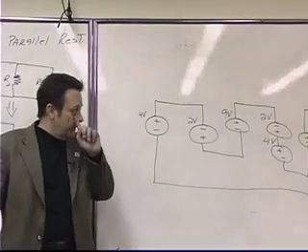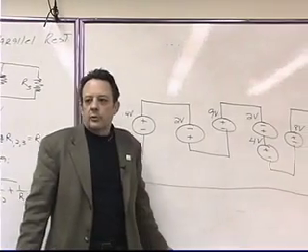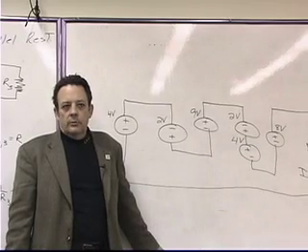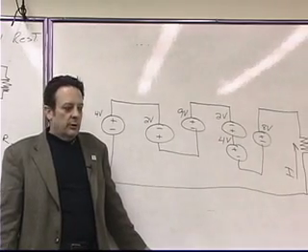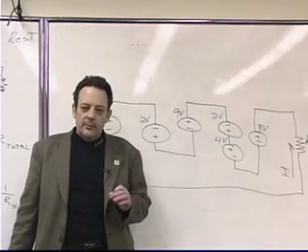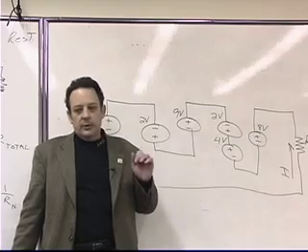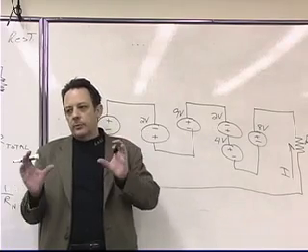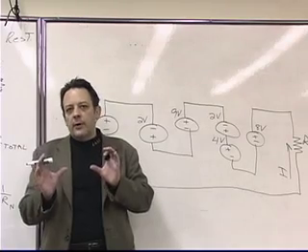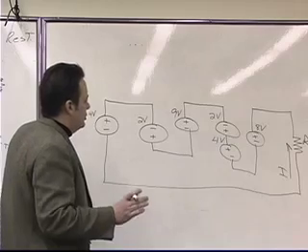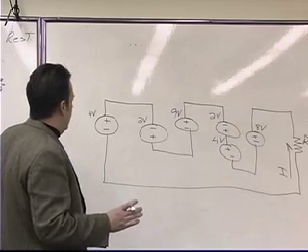Now, what's the first thing that you're going to do to simplify this problem? Right. What you want to do is add up the voltages, but you need to be real careful when you add them up, because if you get the polarity switched around, you might have two of them cancel each other out when in fact you should be doubling them. Okay? So let me show you the approach that I use.